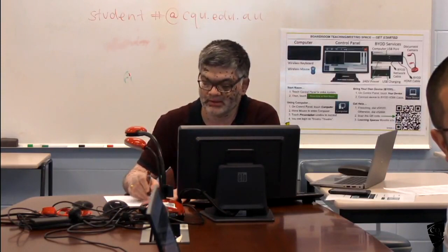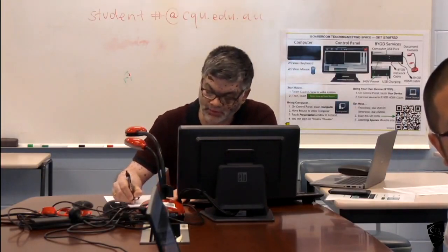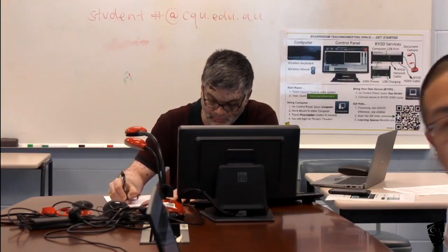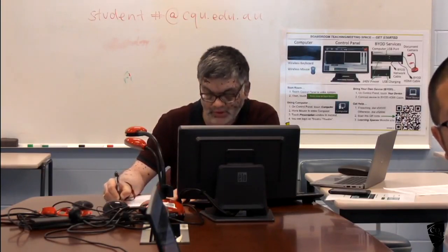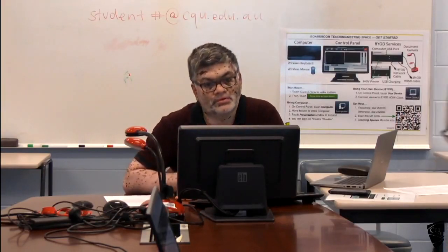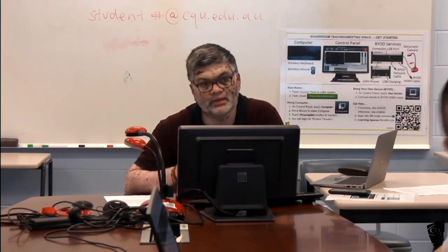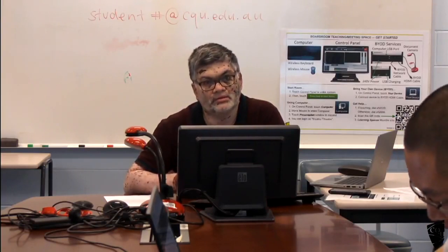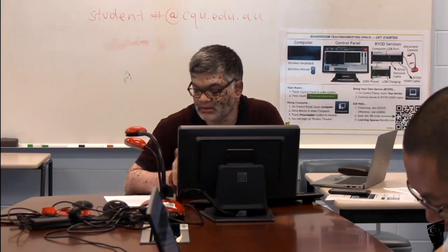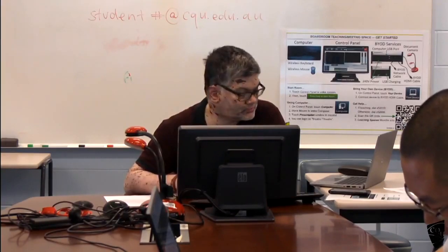So this one, you may have deflection in both directions, X and Y direction. So generally use the shorter span. Use the shorter span for this one. Okay, you have to use the shorter span for such situations.